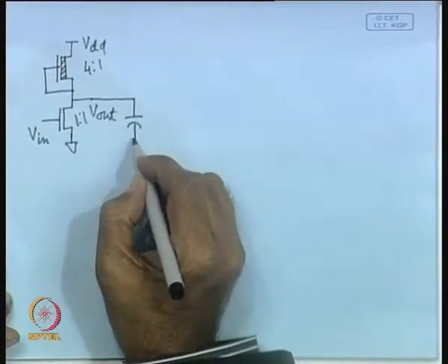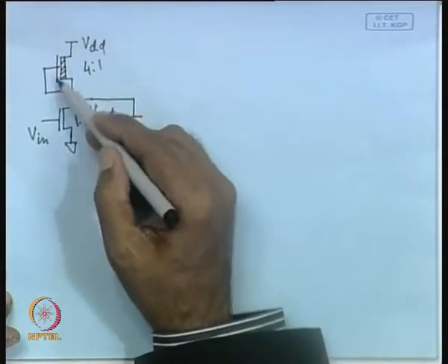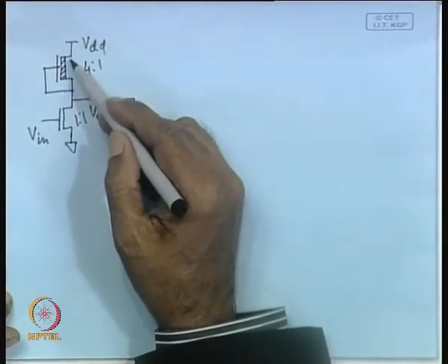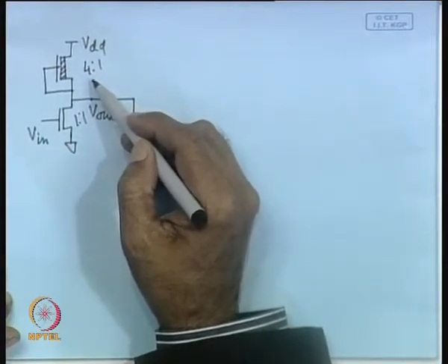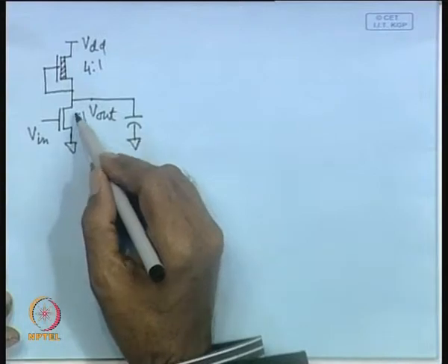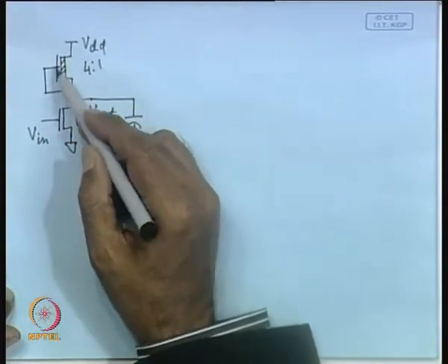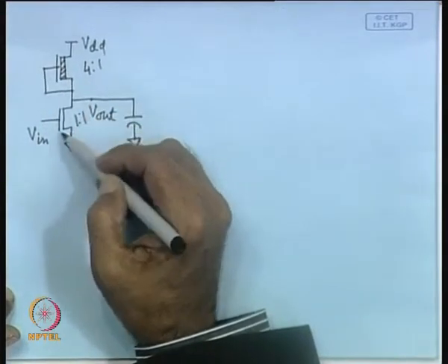So, whenever this is a situation, there is an asymmetric behavior in the switching characteristics, and whenever you are charging and discharging a capacitive load, that means it has to be charged through this device having length equal to 4 into 2 lambda compared to here it is only 2 lambda. So, that means resistance of this device is at least 4 times that of the pull down device.